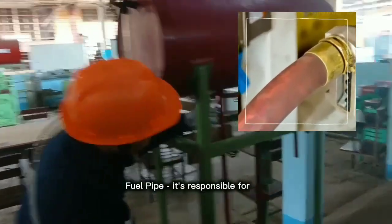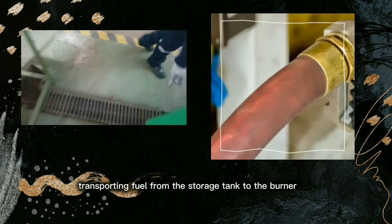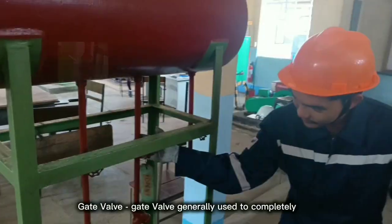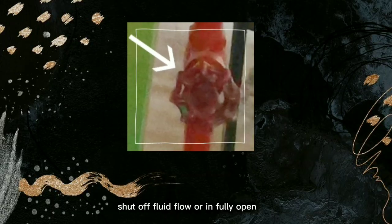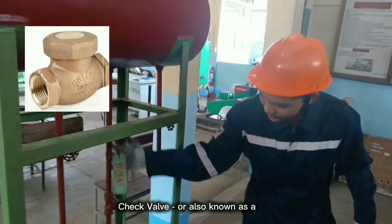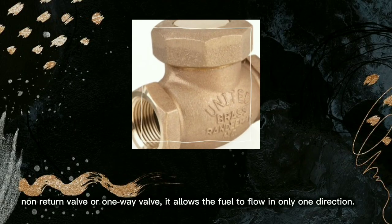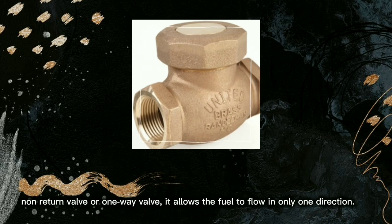This fuel pipe is responsible for transporting fuel from the storage tank to the burner, where it will be ignited and used to generate heat. This gate valve is generally used to completely shut off fluid flow or, in the fully open position, provide full flow in a pipeline. A check valve, also known as a non-return valve or one-way valve, allows the fuel to flow in only one direction.